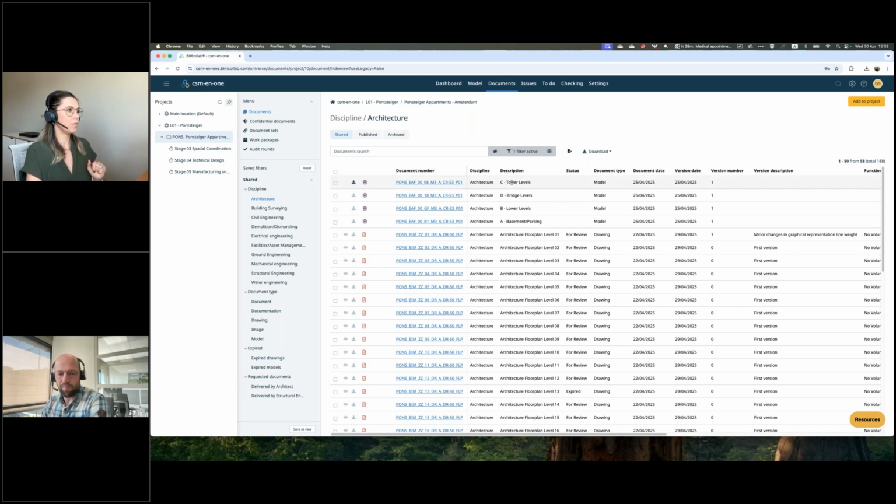But if you don't have access to Twin, only to Nexus, and the model is coming from Twin, you can still see it if you have the permissions, of course, if they are uploaded at the project level. When we go to the more advanced setup and permission settings and go to phase level, then it has to be the active phase to be shown in Nexus, not all the different phases. But maybe it's going too deep in answering that question. Do you have any other remarks, Gijs?